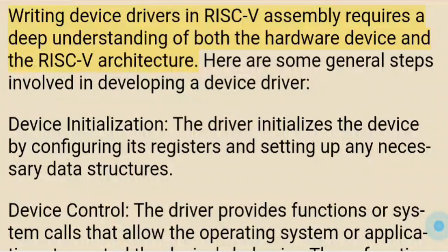Writing device drivers in RISC-V assembly. Writing device drivers in RISC-V assembly requires a deep understanding of both the hardware device and the RISC-V architecture. Here are some general steps involved in developing a device driver. Device initialization. The driver initializes the device by configuring its registers and setting up any necessary data structures.